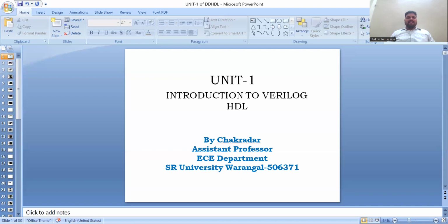Next is register transfer level. Designs using the register transfer level specify the characteristics of a circuit by operations and transfer of data between the registers. An explicit clock is used here. RTL design contains exact timing bounds, and operations are scheduled to occur at certain times. Modern RTL code definition is any code that is synthesizable, which is called RTL code.